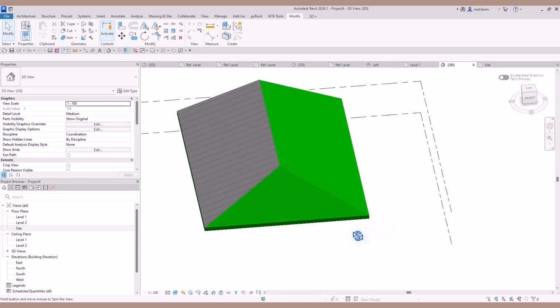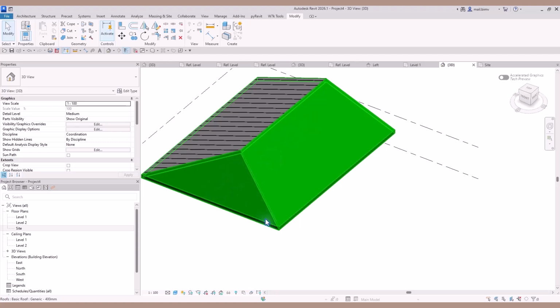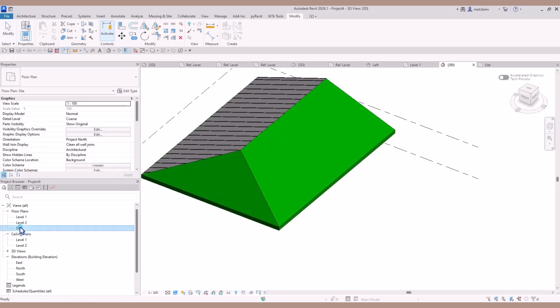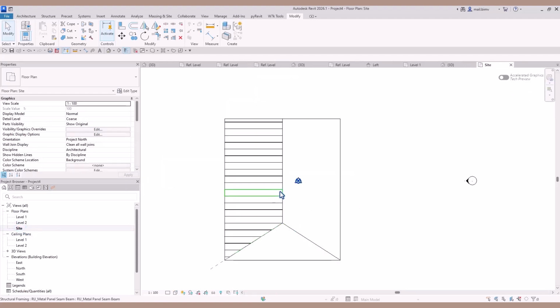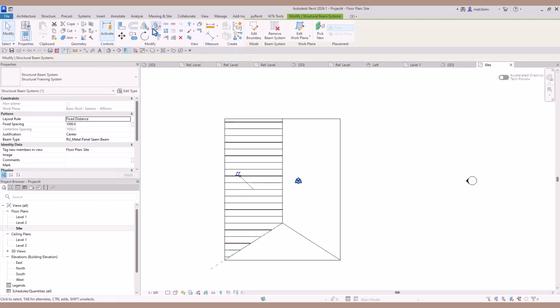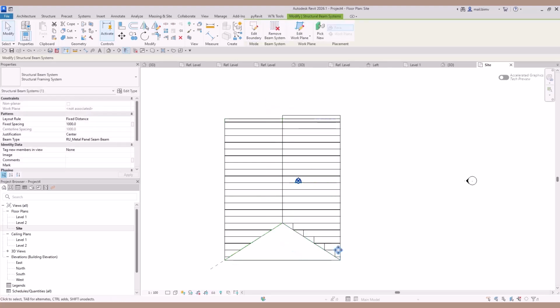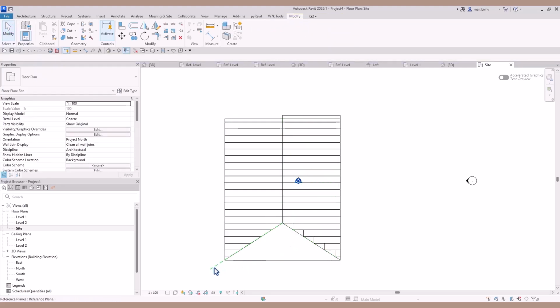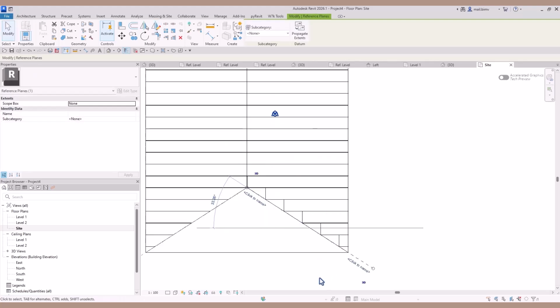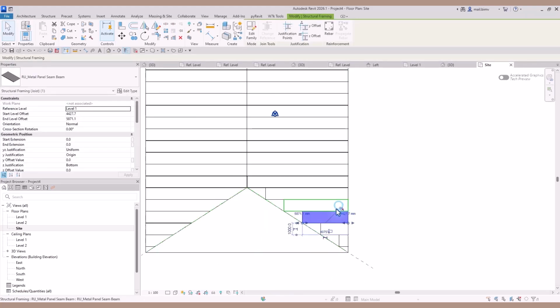We would follow the same pattern on the other side and also on this side. I can even mirror that by drawing a line along this edge. Okay, I would have to extend it and fix it a little bit. So I would also have to copy this reference plane, and extend it by unpinning these beams for a second.